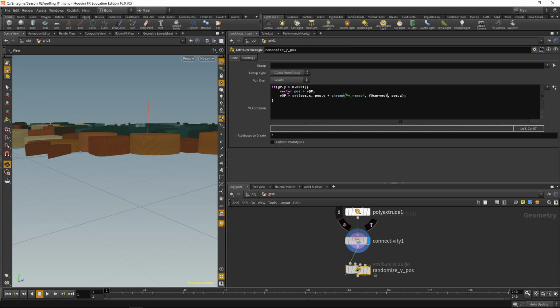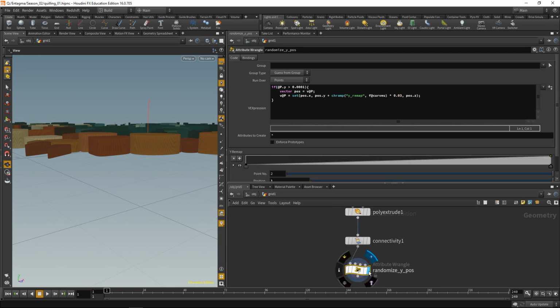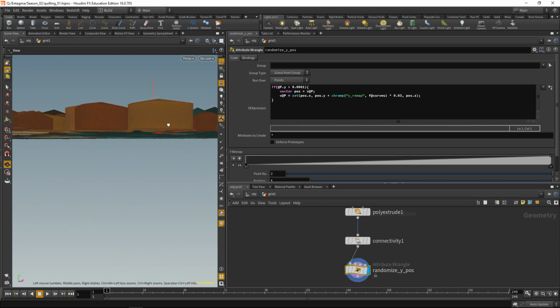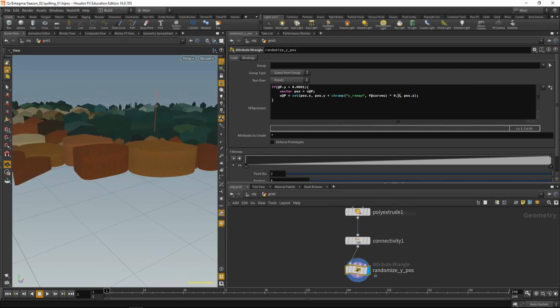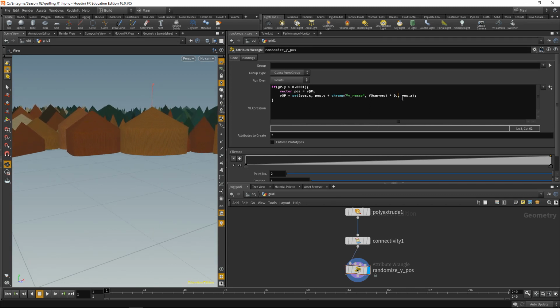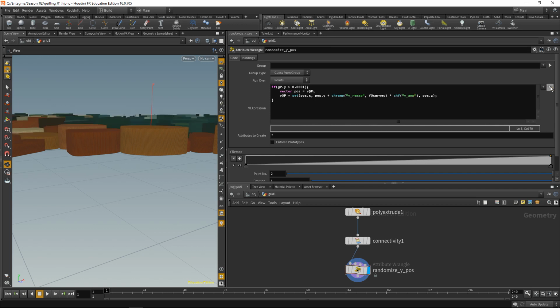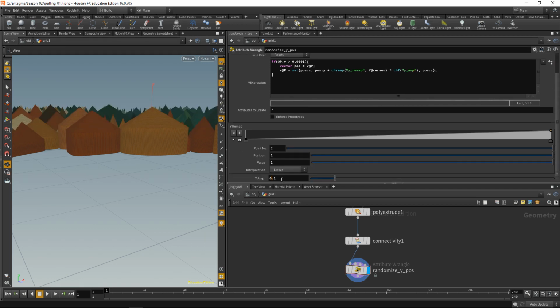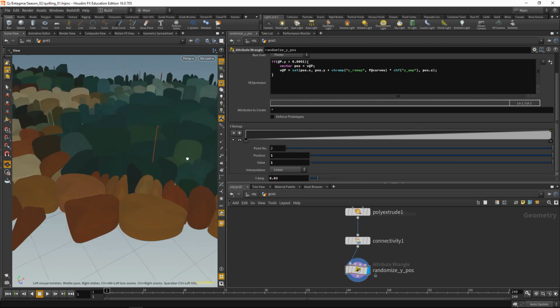And let's maybe add a scaling factor, because otherwise those extrusions would get really big. So let's multiply this by something small, let's say 0.03. Let's create this and highlight our node. We can see now we have those slightly upward spirals. And again, I can change that amplitude in here, like so. And maybe let's create another slider for that. Let's call it Y amplitude. Add the slider in here and maybe dial it up to 0.03. I like that. Okay.